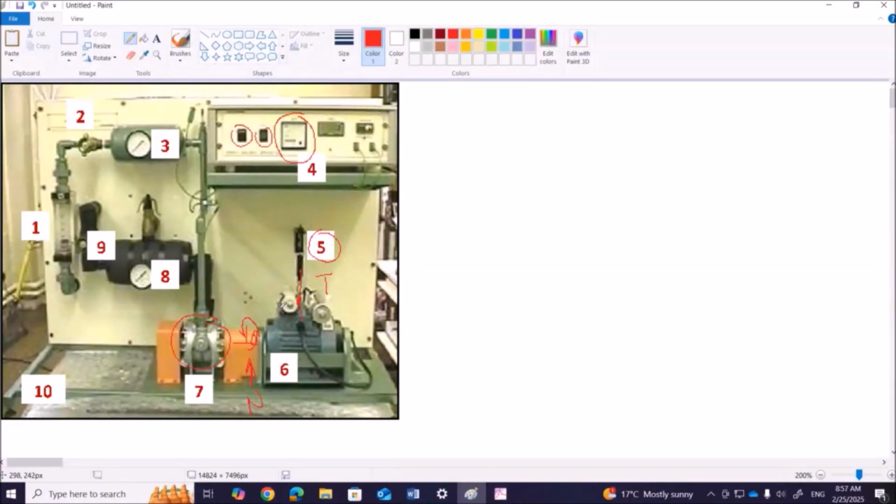When the electric motor runs, there is a jerk. The electric motor will make a jerk, and that jerk we can measure by using the mass spring balance, and the length of the arm times the mass will give the torque. That mass is converted into Newton. The force is equal to mg, so we get Newton, and the length of the arm is given to you as 0.2 meter. So we know the length and we know the measured mass, so we can calculate the torque. I will explain this in detail later on.